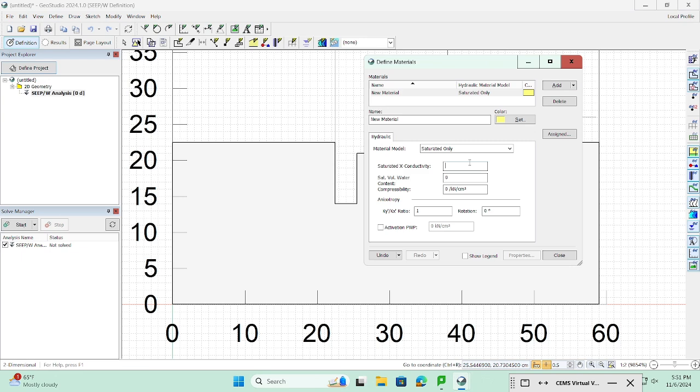And enter your constant head conductivity value. You did a constant head test, as you can remember, in the same lab, and you did it for 3 or 5 different times. The average for the conductivity should be added here. I will assume that the conductivity here is 0.009, okay? This is just a value that I made up, but you should add the value that you have from the lab.